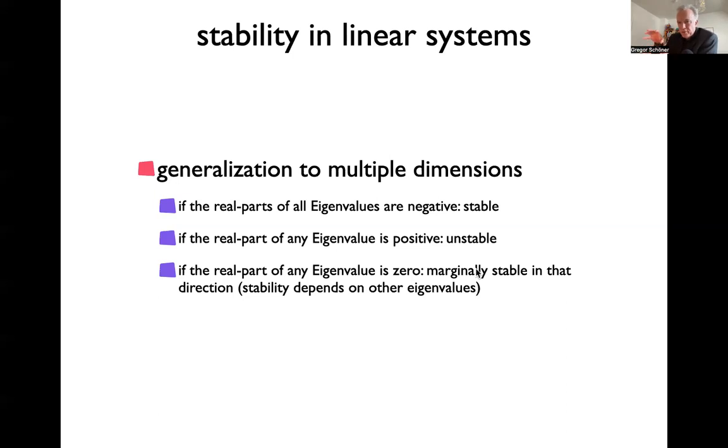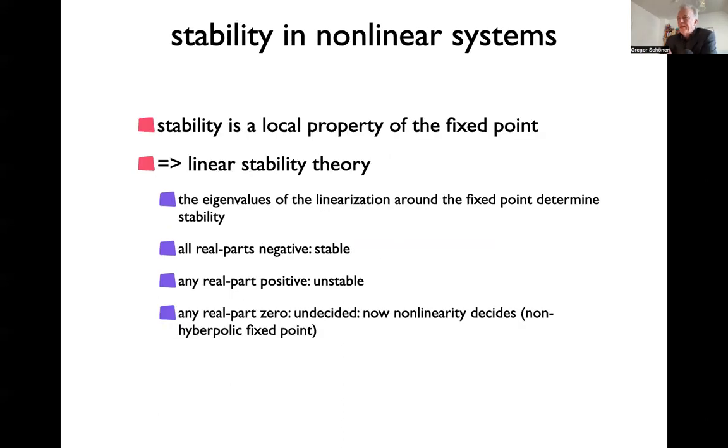Only then do you get really attraction. If there's a single direction in which you would diverge, then there's no guarantee that you're going to be attracted. So control theory is very much about fixed points. The set points of a control system are made fixed points that are asymptotically stable. That's how stability is used in control thinking, right? Just to connect that. Now, how about nonlinear systems?